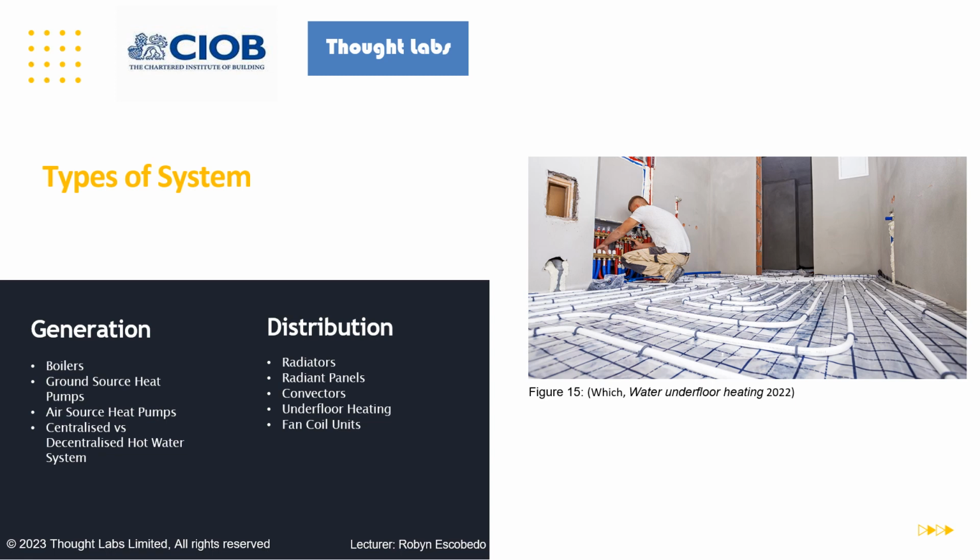There is a relatively even heat distribution throughout the floor, and the temperature is not hot enough to burn your feet. So it's much safer and much more appropriate to use these in situations such as schools and healthcare where there are vulnerable occupants. However, in situations like offices or receptions where there are floor boxes and trenching that are providing power to remote desks, power to sign-in screens, etc., then underfloor heating may not be the most suitable, as it may clash with the dado trunking that's providing the power and the data.